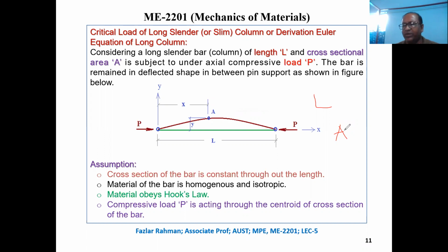You have two options. You can measure with a tape, right? Even if you measure with the tape, say a column is 200 feet long, you'll say this is a long column. But if its cross section is too high, it might not behave like a long column. It might work like a short column. Similarly, a very small column whose cross section is very narrow or very low, though it is short, might not behave like a short column.